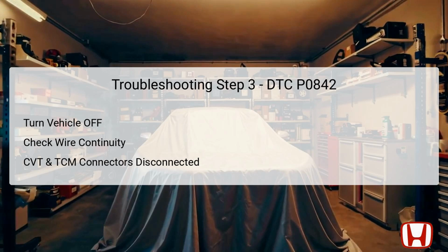A continuity test shows whether electrical signals can pass through successfully. If continuity exists, then it is confirmed there is a short to ground in the wire leading to the TCM. This step guides technicians toward isolating and repairing the fault in the circuit.